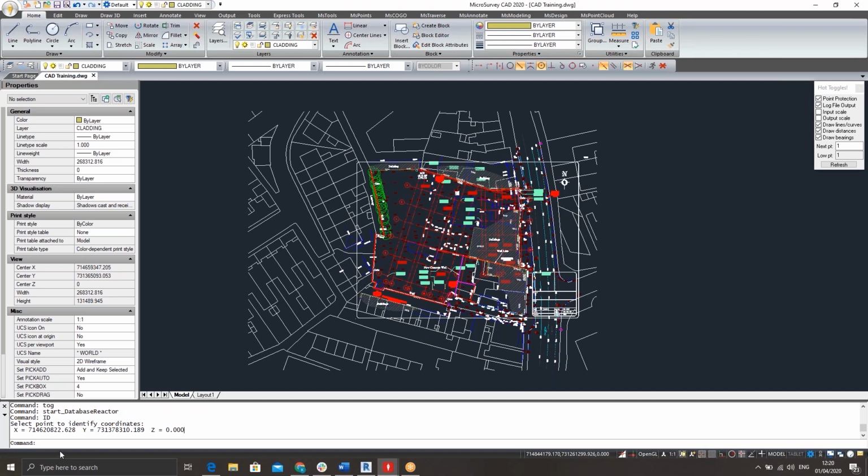But first, before we move on to that, I just want to note we need to understand coordinate reference system. So is our drawing referenced, is it relative to a national grid that's transferable so we can locate our objects relative to each other within the site? So the first step within IDing the point will give us an indicator whether the drawing is in millimeters or meters, but the real issue is for it to specify whether the drawing is referenced or not. So what coordinate reference system is used? So I know by identifying that point and looking at the figure starting with 7 and 7 that I'm currently working within Irish Transverse Mercator.